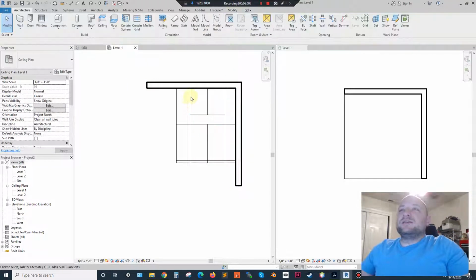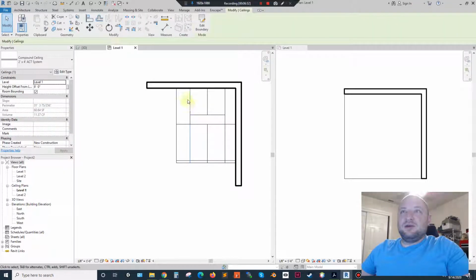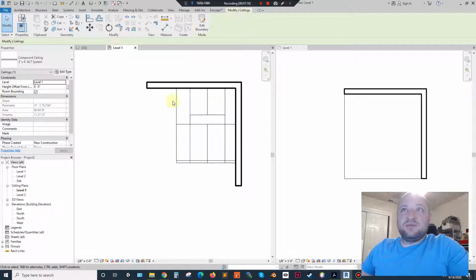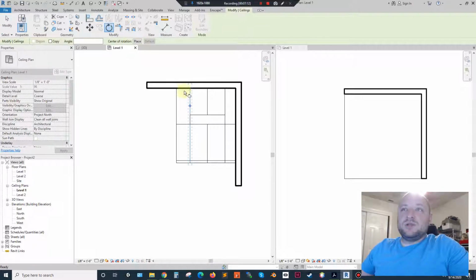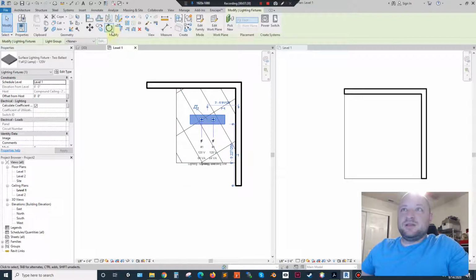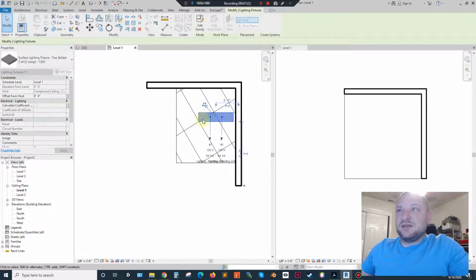While we're looking at this, I think it's also worth mentioning, it hasn't come up yet this term, but often students want to know, how do I rotate? Like maybe I don't want these ceiling panels this direction right here. So what you do is just deselect everything, and you can do this with floors as well. So anytime you have a wood floor and you want to change the orientation, you can just click on one of the lines there, and then do the rotation tool right here, and that'll just rotate the orientation of those panels.